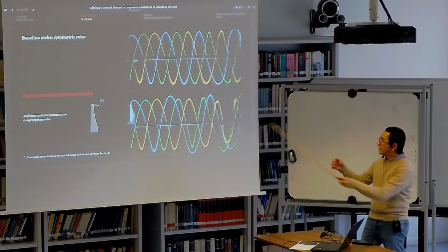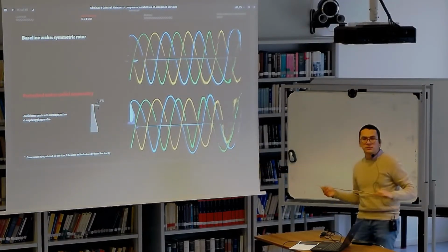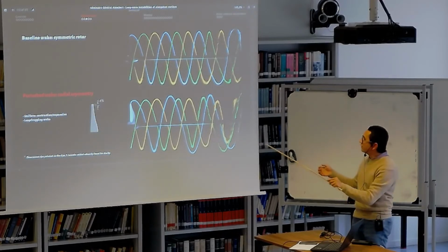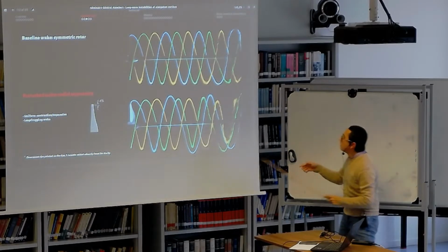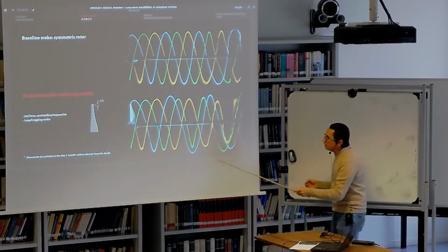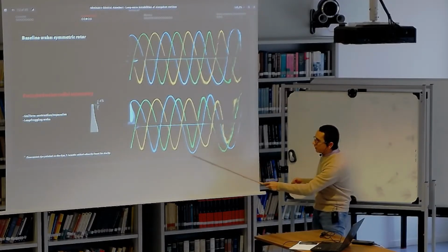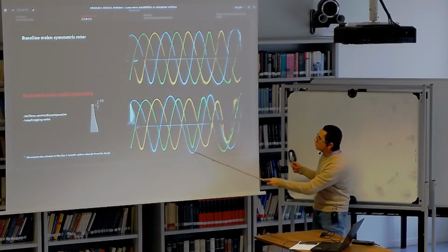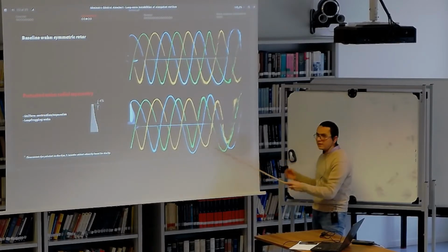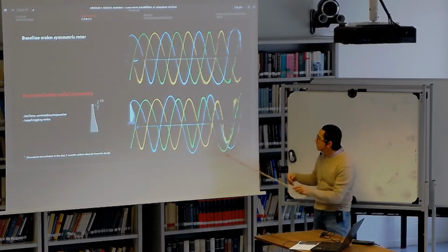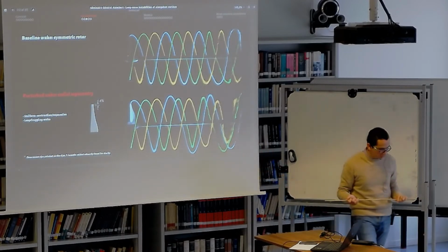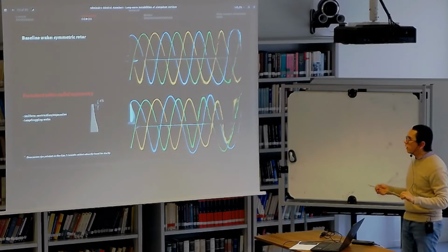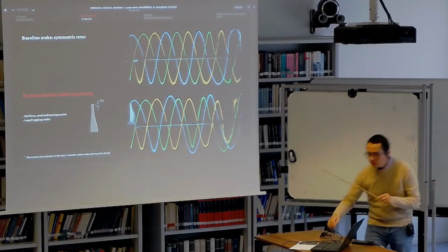So if your blade is slightly longer, you have this change in the structure, and this is interesting because we have a couple things to mention. For instance, when the vortices are trading places, this is also the moment where they're very close to one another, and we believe this is going to induce or at least accelerate some of the shortwave instabilities that appear later. And we can see that some of the vortices actually seem to break down a little bit faster. So this seems like one option.